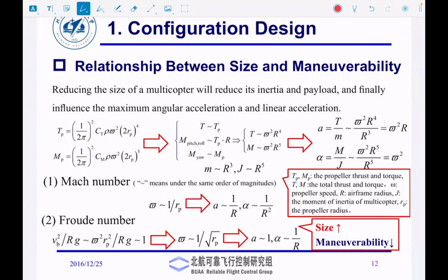I don't know if you have studied this, there is something called the Buckingham pi theorem, which is used for dimensional analysis. So what you do is, basically you find the dimensionless numbers. And then if this dimensionless number for this airframe is the same as for this big airframe, everything would scale up accordingly.